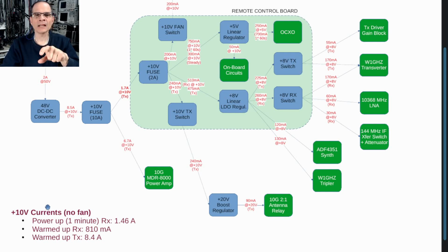Imagine if I had decided to send the 10 volt supply up the tower on around 60 feet of cabling. We would have had a significant voltage drop on the line. And the best thing to do was to regulate up on the tower and send a much higher voltage, which allows me to reduce the current to a maximum of 2 amps, which 20 gauge wires can easily carry up the tower. And even if there's some voltage drop here, I do not care.